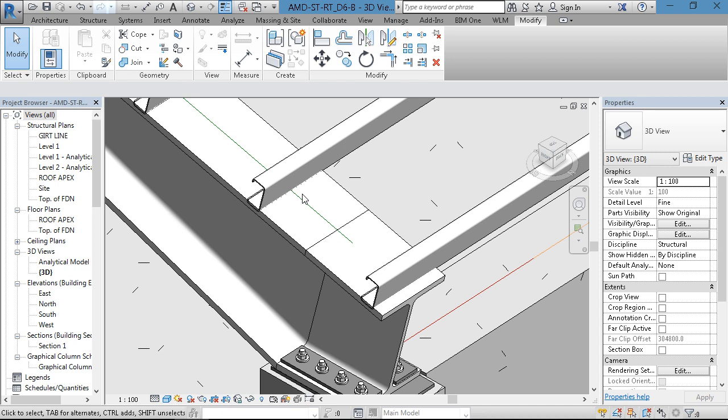And then go to your family types. And then click that purlin length. Click here. And then click that pencil. Set that one to instance. Then click OK. Instance means that you can stretch. Then save and reload it. Save. Load up to your project.